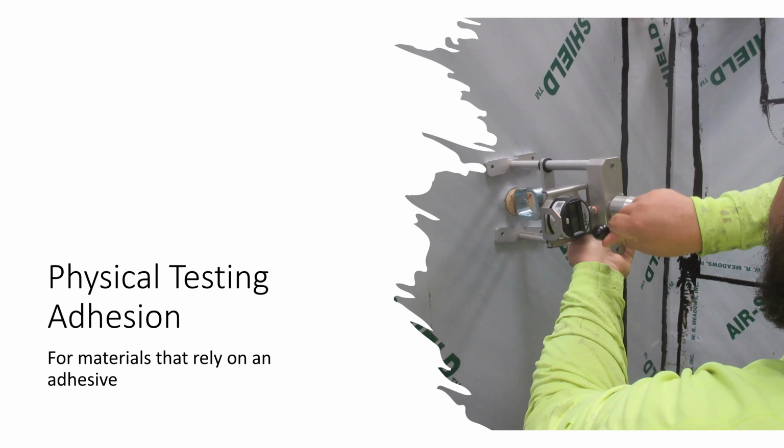The way I interpret that section of the 2021, you have to blower door test, depending on climate zone and building type and size. There are some instances where you have to blower door test. It'll say shall, and then later it says, well, if you don't, then you can. And I was like, well, if you shall do something, there shouldn't be a follow-up with that if you don't. I'm needing to submit to ICC for an interpretation on that one.